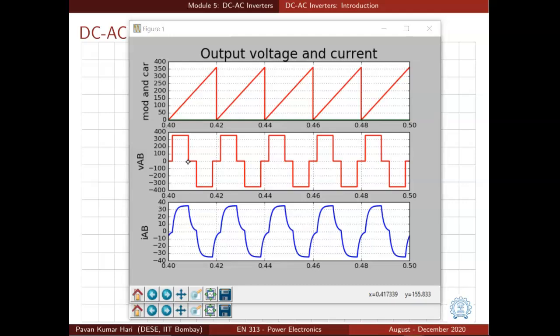The 0 interval is adjusted such that there is no third harmonic, no ninth harmonic, there are no harmonics of the order 3n in this case, and the current waveform looks a little better than that with the square wave, as seen from the third figure, the blue color waveform.